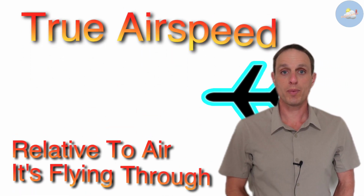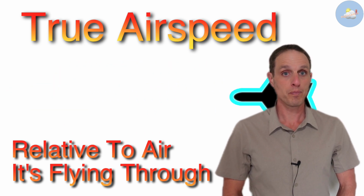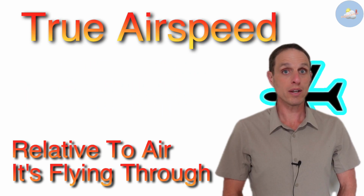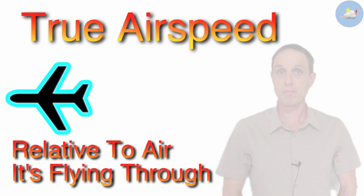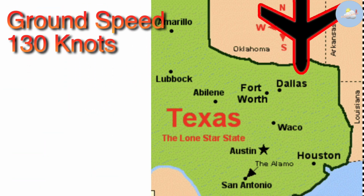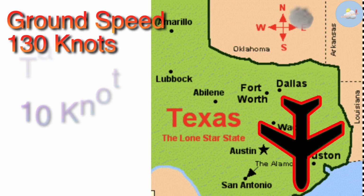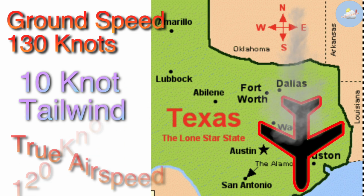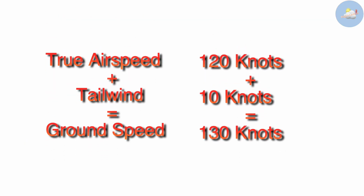Next is true airspeed. This is the aircraft's speed relative to the air it's flying through. The relationship between ground speed and true airspeed is where wind comes into play. Imagine a plane flying from Dallas to Houston. Air traffic control sees its ground speed as 130 knots. What they can't see is that it's getting a 10-knot push from a tailwind. The plane's true airspeed is actually 120 knots. So true airspeed plus tailwind equals ground speed.